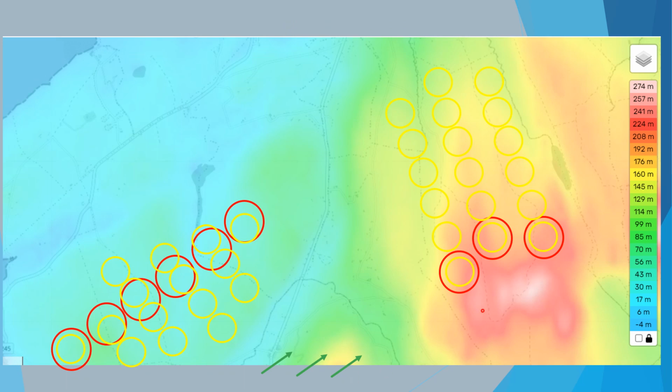You can see that some of the turbines here are on high land. They're away from the peak, so I've still included them, but they could potentially end up being unfeasible. It's also worth noting that the turbines here were intentionally placed upstream of the mountain, so that the vast majority of these turbines should be completely unaffected by the wake from the high altitude here.